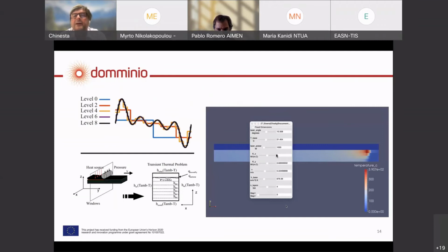You are applying a heat flux, and you are trying to move with a certain velocity. There are many properties, as you can see on the right, the conductivity, the velocity, the angle in which you are applying the heat, and we just add 2 new parameters. This image is the first time that you can see it, because now the important thing is you have the temperature of the substrate, that is important, but you have also something that is very important, H in the substrate. That means the thermal resistance between the tape and the substrate.